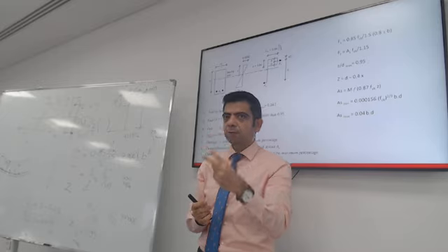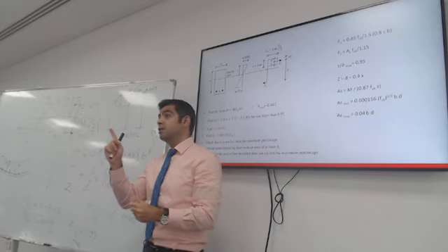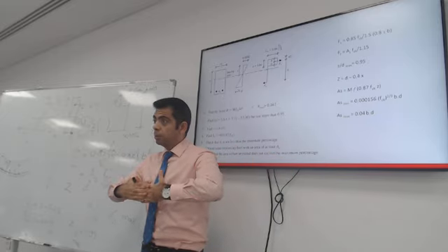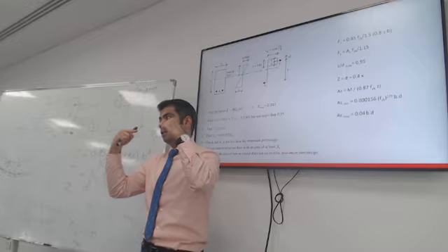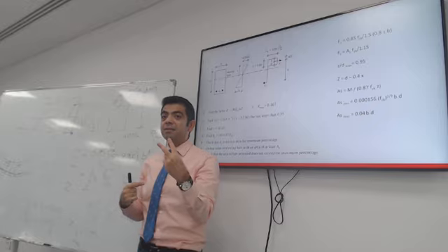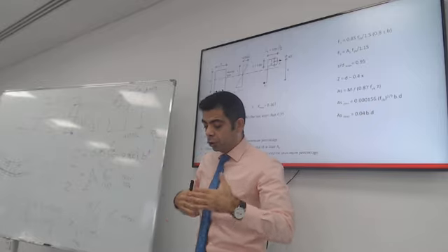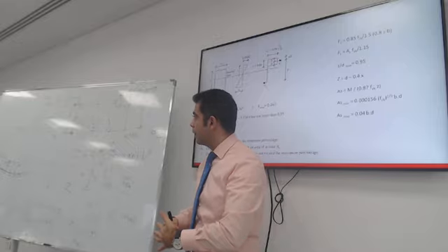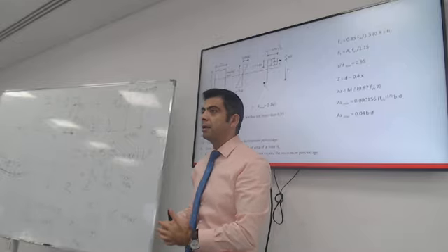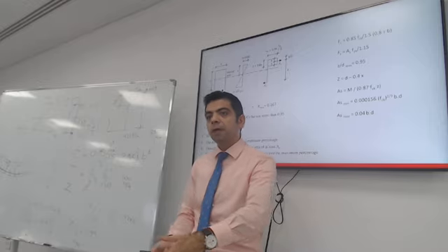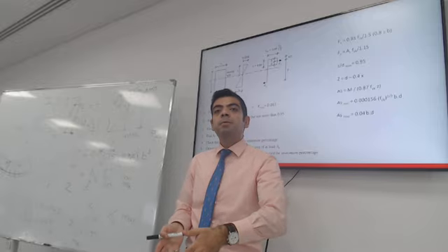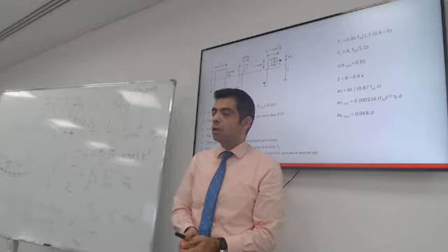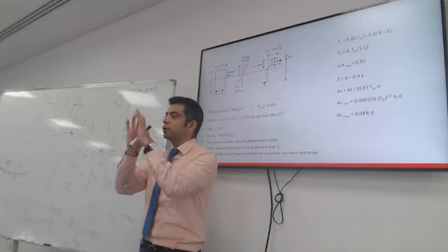For two reasons. If you put too much steel, the steel bars will be too strong and you'll have compression failure. The second reason is if you put too much reinforcement in the bottom, you cannot fit the rebars together. This is for constructability. You can express it as a percentage of the cross section.